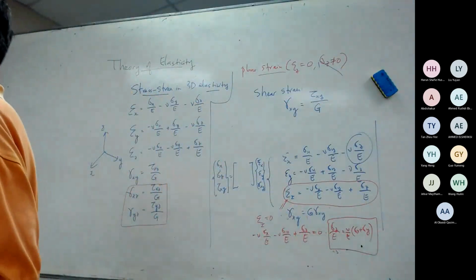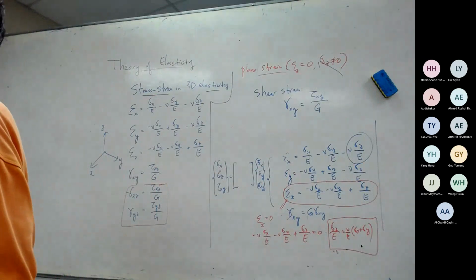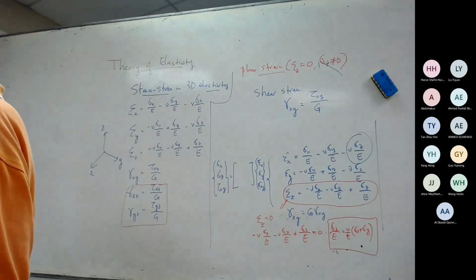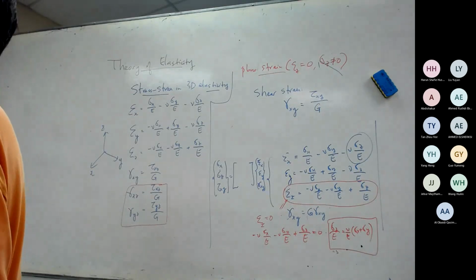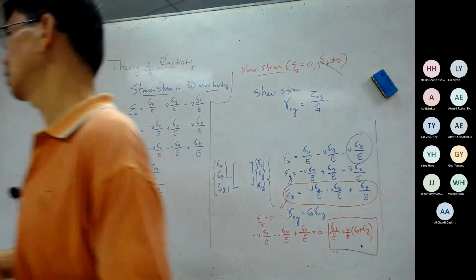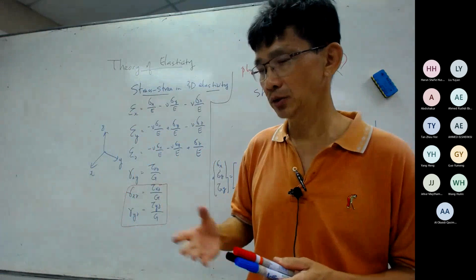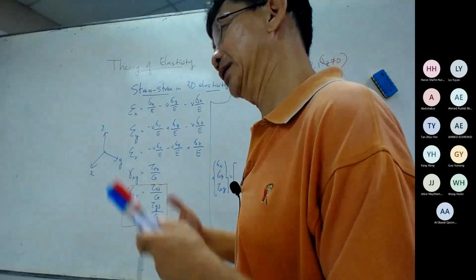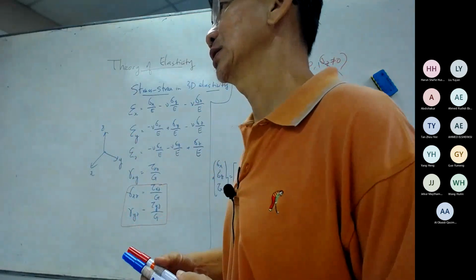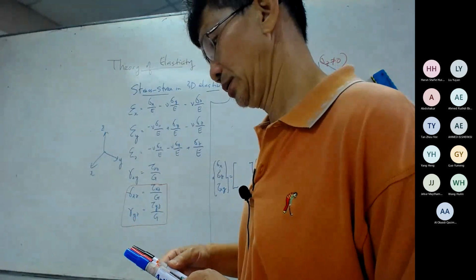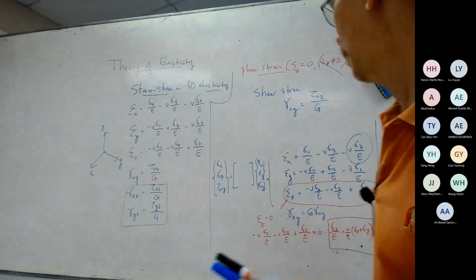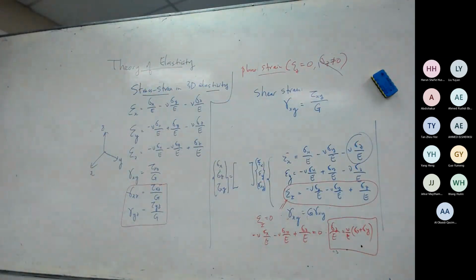So Harun, the question is, can I get the value of shear strain without G? You can get the shear strain without G if you relate that to the change in shape. If you can measure the change in shape, and especially if you know the change in angle in the XY plane, YZ plane, or XZ plane of an element, then you can get the shear strain. Let me pause here before I go to the next one.